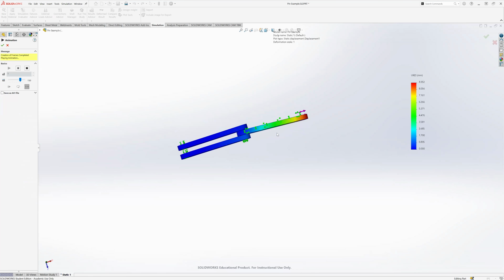And this is another thing. So then I'm going to put another roller slider here. One thing with SolidWorks Simulation that's actually rather odd, but pretty typical for FEA packages, is that from a physical problem you would think about, like in statics, when you apply a force here and you're fixed here, you would not think it would be able to move this way, because it really shouldn't be able to move this way.